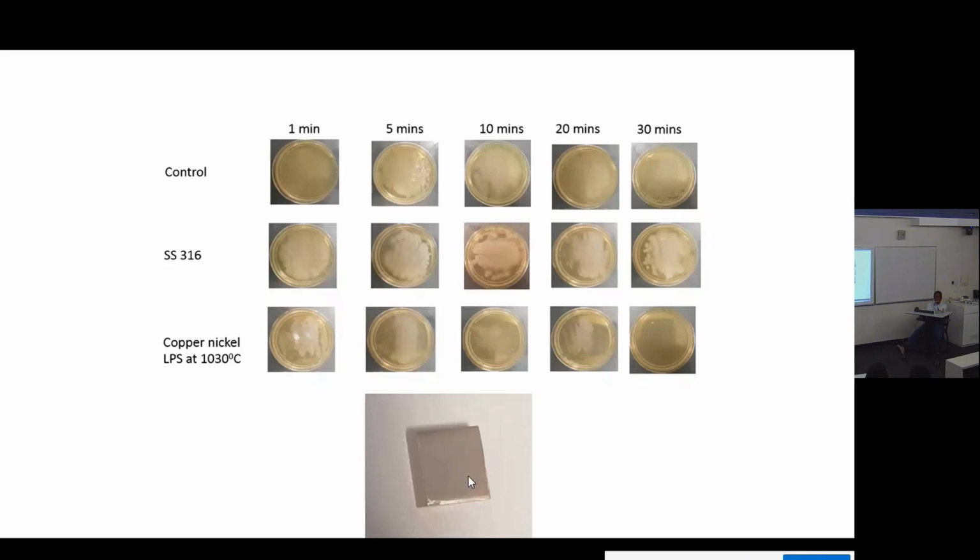So one thing we are not sure about, even though I've not measured, I have not seen this anywhere else: cast parts anyway will have very poor impact resistance. I would think the same thing would be with the cold spray, but I'm not sure. It has not been measured yet. In terms of other properties, we're fine. Yield strength and tensile strength, ductility, hardness will be all okay.